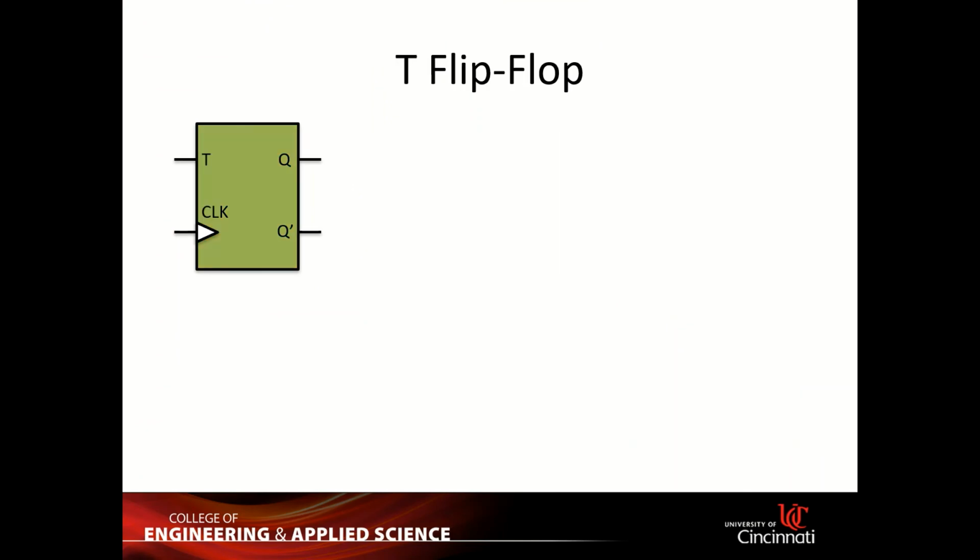Okay, next one. This one is way easier. So the JK flip-flop, the positive thing is you can decide when to, it can do more things than just the D flip-flop, right? With the D flip-flop, technically all you can do is transmit the data through when the clock cycle comes, and you can hold the data by not putting the clock into the D flip-flop. The JK flip-flop can decide what type of output you want to bring to the next state. So it's more complex there.